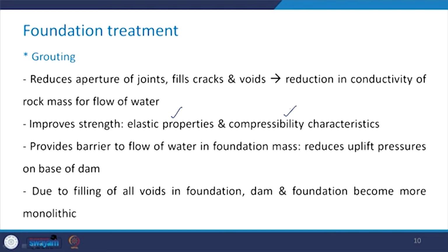It also provides a barrier to flow of water in the foundation mass, thereby reducing the uplift pressures on the base of the dam. Now, due to filling of all the voids in the foundation, dam and the foundation become more monolithic. So, these are the advantages of the grouting.